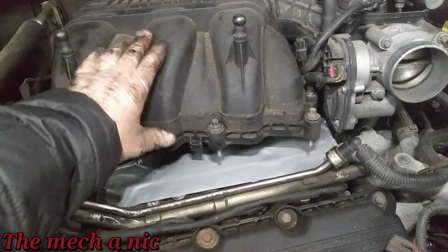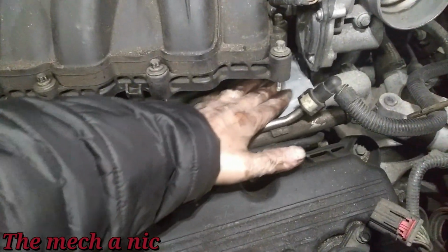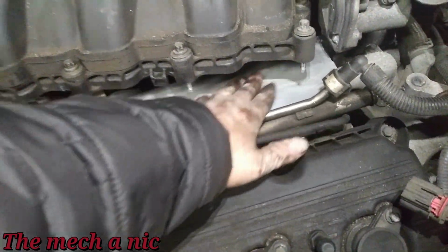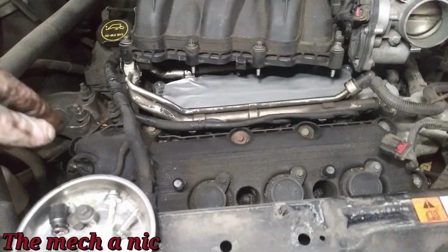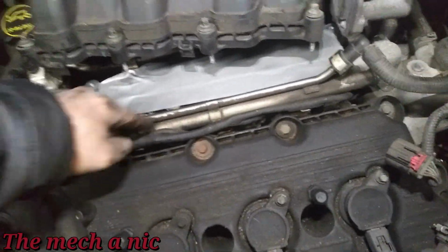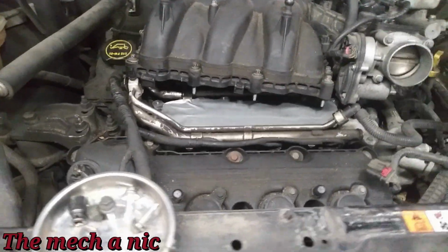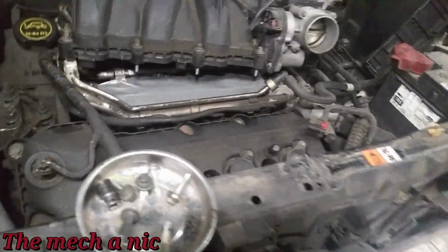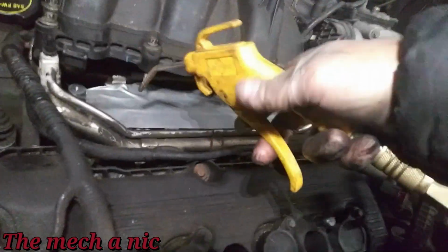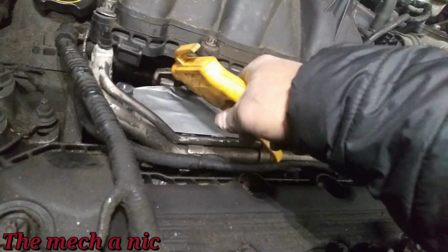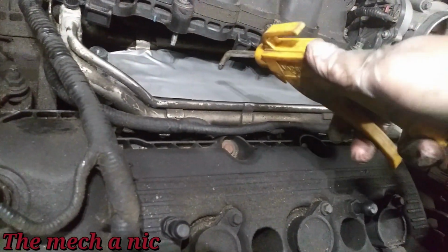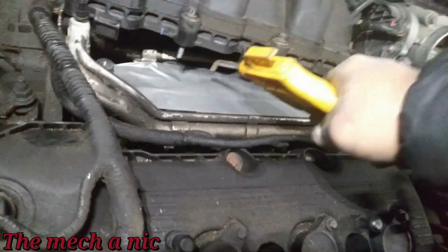Remove the intake manifold, and we just got it propped up here just enough so we could get clearance. You can see I put some tape right here on the intake runner so nothing falls inside of there. I've already removed all the bolts holding down the fuel rail, but before we actually go ahead and get it out, I'm gonna go ahead and use some compressed air to knock out any junk that's sitting down in this valley right here,